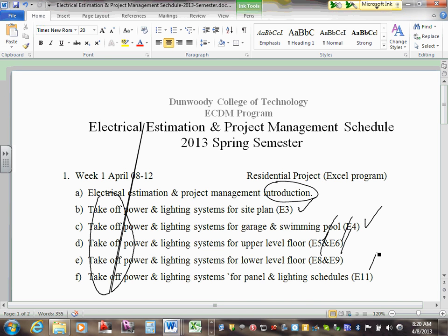So you're going to grab this big fat fluffy sheet and put it in front of you and your partner. You're going to have colors. I want it colored, guys. We'll tell you the color code you're going to be using. You're going to color the components as you count them, and put them in the software that I gave you, in Excel. This will be done in Excel. It spits the information out for you. When you're done, you're going to give me these sheets colored as part of it. I need them as proof of takeoff, and the Excel sheet will be in your team folder. Does everybody understand what you guys are going to be doing when I say takeoff?